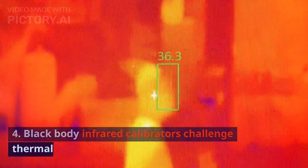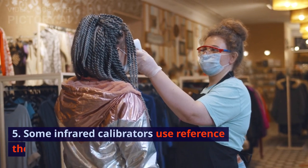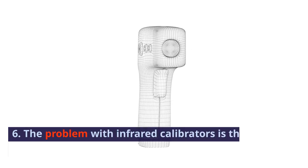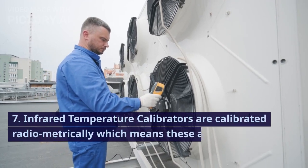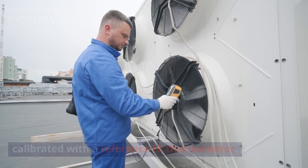Black body infrared calibrators challenge thermal radiation. 5. Some infrared calibrators use reference thermometers such as PRT or thermocouples. 6. The problem with infrared calibrators is the variation in emissivity. 7. Infrared temperature calibrators are calibrated radiometrically, which means these are calibrated with a reference IR thermometer.